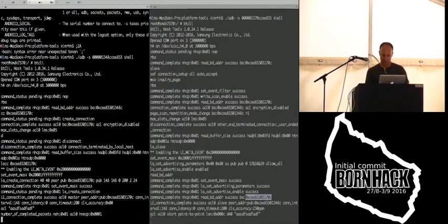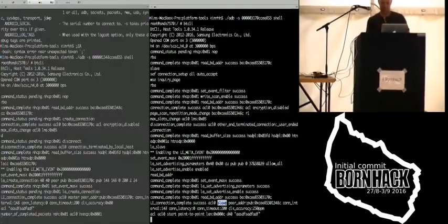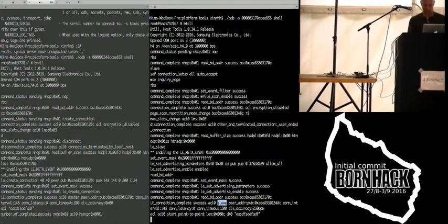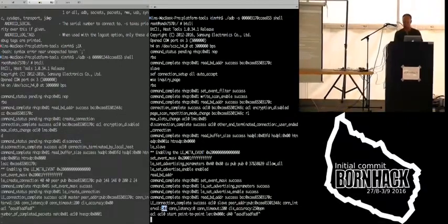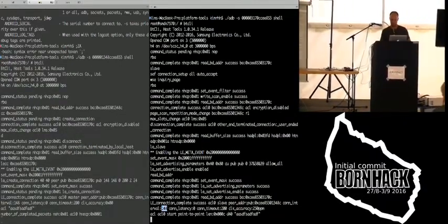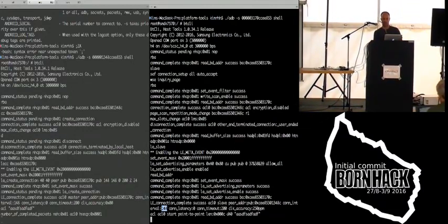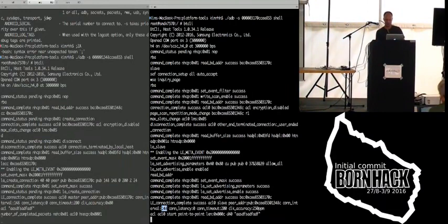It says when the connection comes up that on this connection, this device is the slave device. It has a connection interval of 148, and I must admit I don't recall what the unit is. I think it might be 625 microsecond slots, but I'm not sure. Anyway, so this is a reasonably aggressive connection. These communicate fairly often.